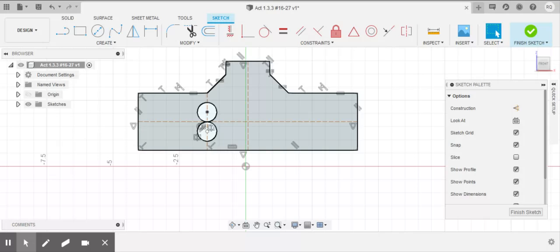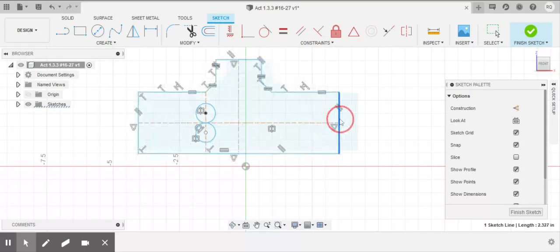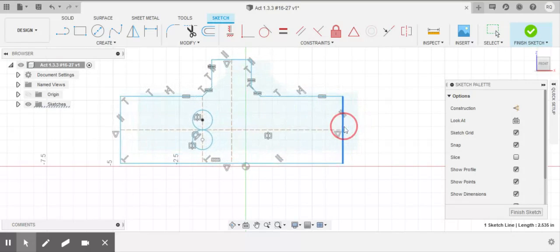Number 26, next we're going to finish up. Is your sketch fully constrained? Check to see if you can move any of the elements, lines, points, or circles. Can you? All right, so let's see if everything's fully constrained or not. Oops, let me hit escape to get out of anything that I'm in. If I move it around, it looks like it. All right, that looks good.